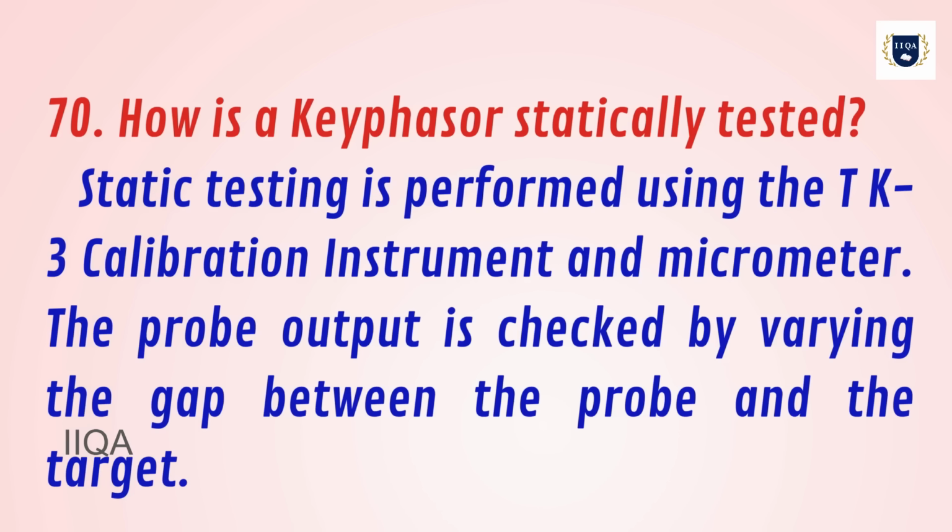70. How is a Keyphasor statically tested? Static testing is performed using the TK3 calibration instrument and micrometer. The probe output is checked by varying the gap between the probe and the target.